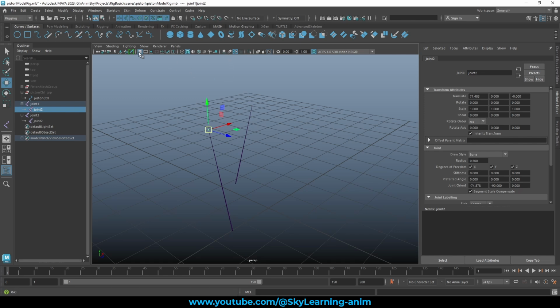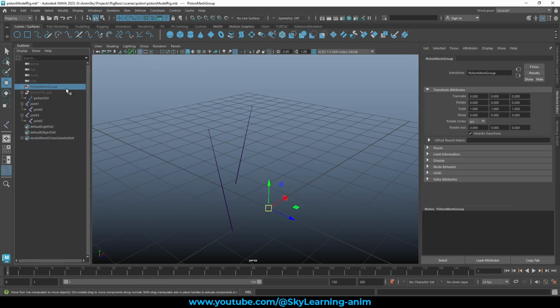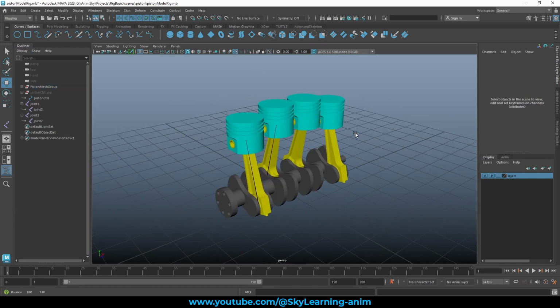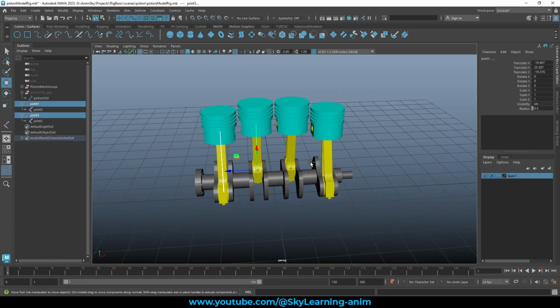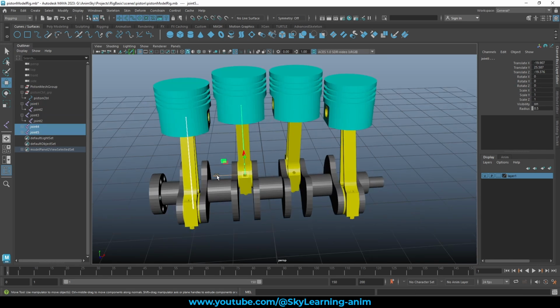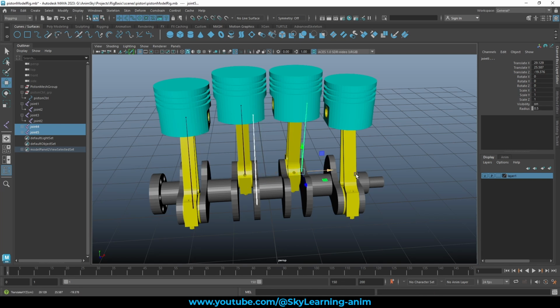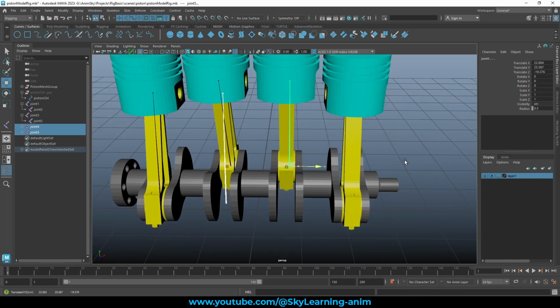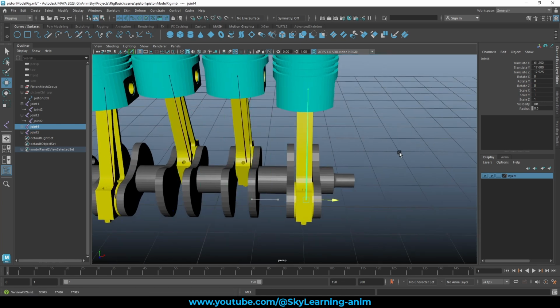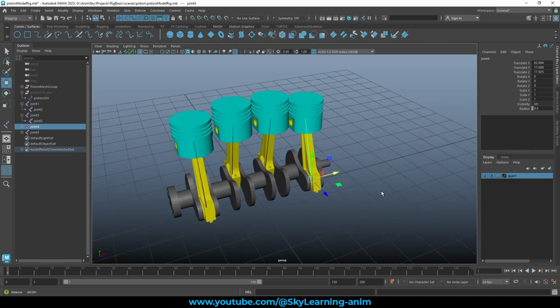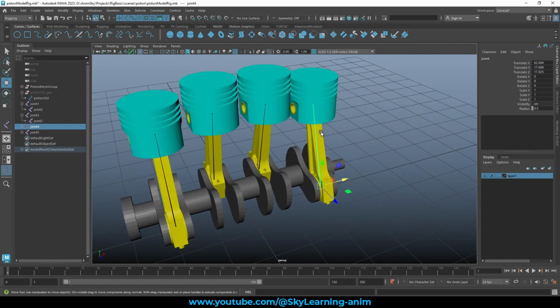All right, so I have hidden from here, do it here, and what we're gonna do, we're gonna duplicate this thing, Control D. Now we're gonna position it over here, go to the world axis, and copy the same joint setup, just get an average center of it because this is going to act in only one axis. So translation in the x-axis will work fine. Even if it is a little bit off center here and there, it is totally fine.